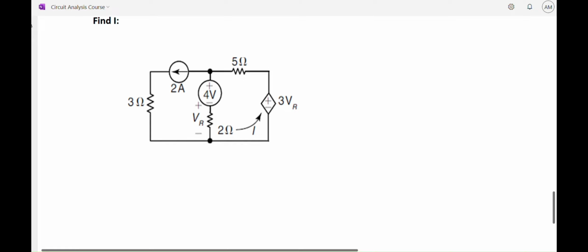So, I start with the reference voltage. Again, I consider this point as my reference voltage. Easy enough for this circuit, because all these points are like a wire, and the wire has a very important factor, which is all those points are the same potential. All these points that I'm blacking are zero potential. So I consider the bottom part of my circuit as my reference voltage.